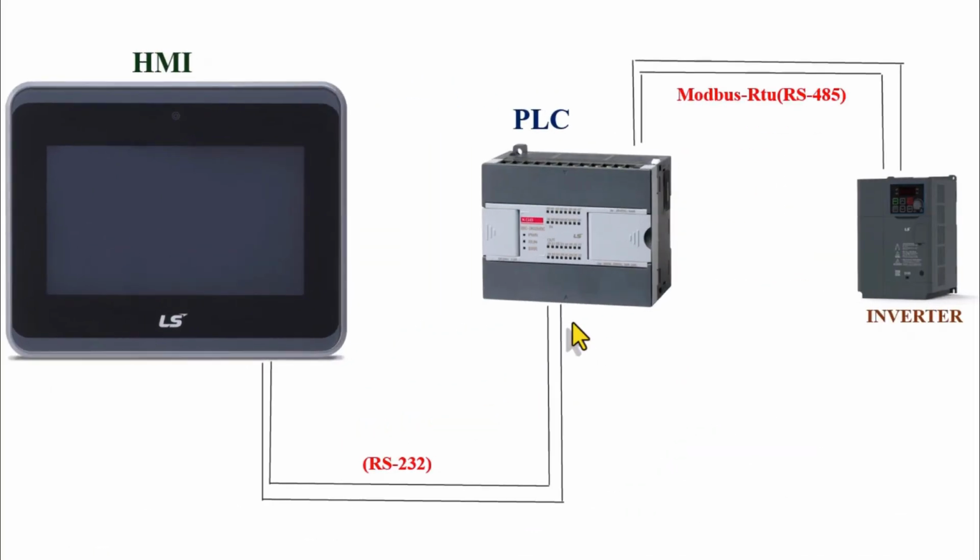Hello friends, in this instructional video, we intend to connect an HMI from the LS EXP2 series to an LS PLC via an RS-232 network and then connect the LS PLC to an LS G100 inverter using the Modbus RTU protocol over an RS-485 network and network these devices together.